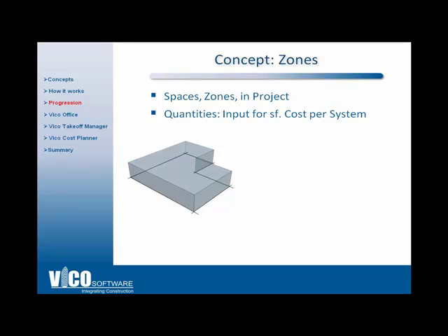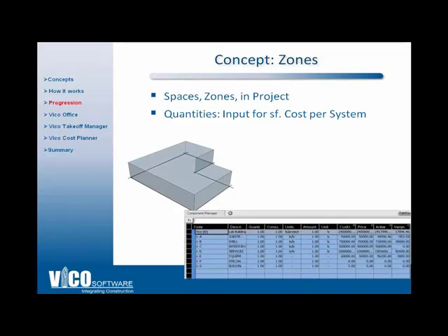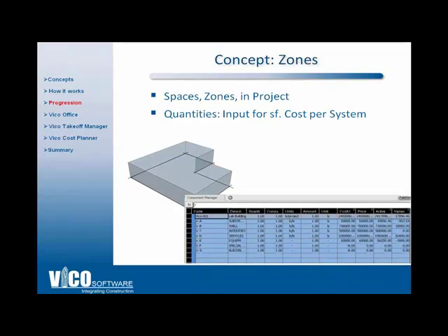You could also break those down to functionality, so you could have the residential tower broken down by unit types and have a dollar per square foot associated with each unit type. And by using the model, you can get a quick estimate based on the geometry and based on the unit per square foot cost of the project itself. So you're working on a high level, you're just working with simple geometry and with dollar per square foot cost.